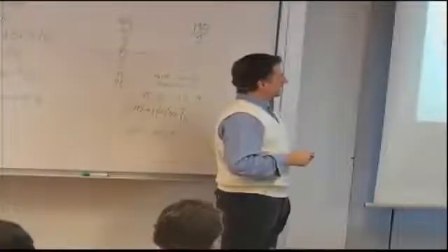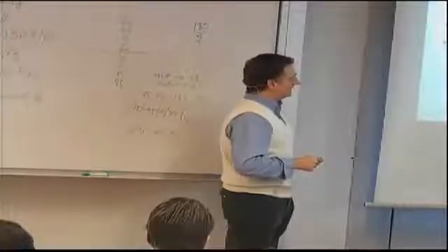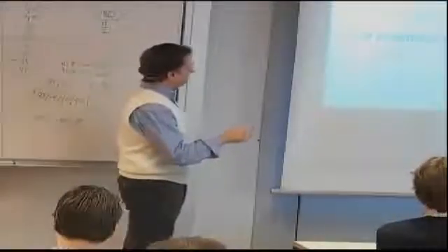We assume that there's no dependence on the z-coordinate out of plane. Basically, it's a plane stress kind of problem, so all the derivatives with respect to z are 0. So my equilibrium equations, the first one had d tau xz dz here, which is not there. D tau yz dz here is not there. And the full third equation, as shown back here, where are my equilibrium equations? Here. So in these equilibrium equations, the last terms of the first two equations and the entire third one, which involves the out-of-plane stresses, disappeared. So that's what simplified things over there.